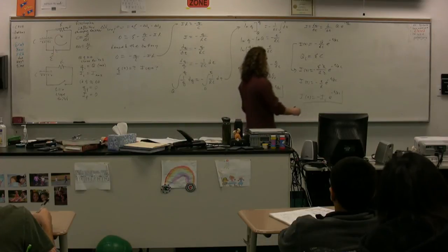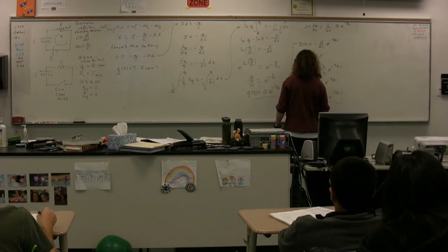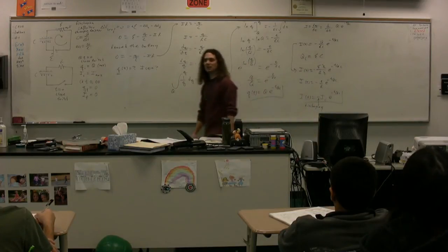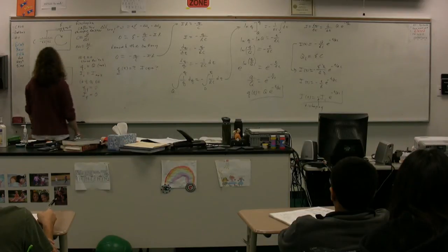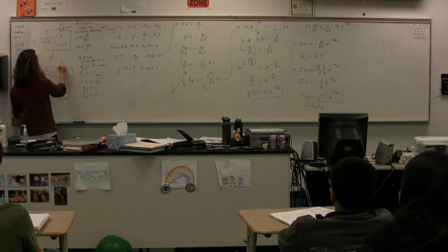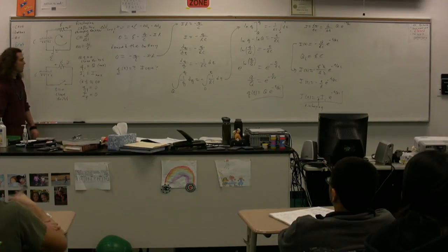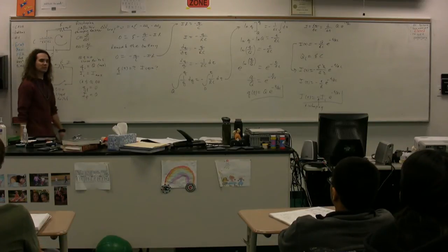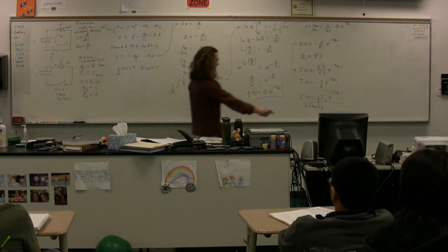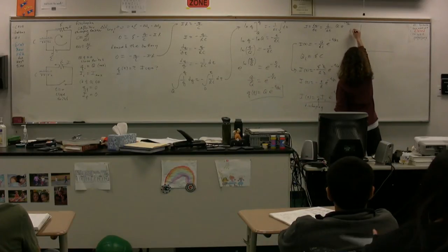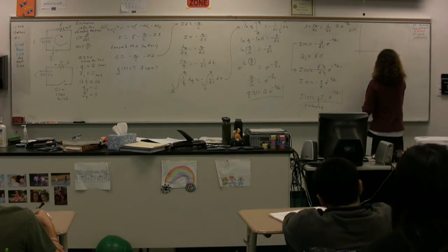I'll just note this negative simply means that it is now discharging. The reason that is negative is because the direction of the current flow now is opposite the direction of what it was before. Because we now have positive charges here and negative charges here, which are causing the current to flow opposite the direction the current was flowing when we were charging the capacitor. That's what that negative means.